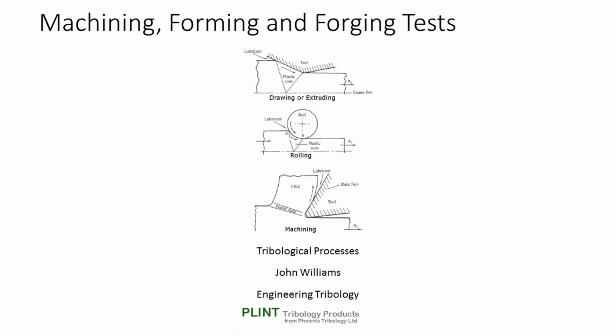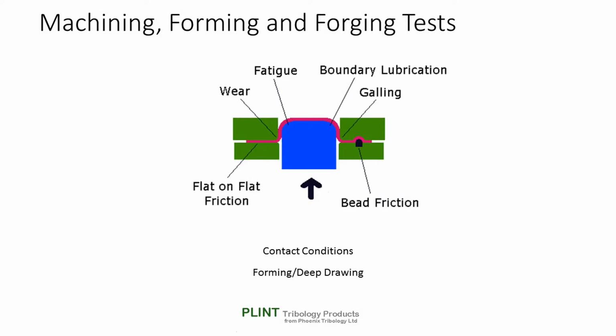It will be apparent from these figures that any experiment that relies on external measurement of force will suffer from an inability to separate deformation or cutting forces from friction forces. Further to this, the majority of such tests will give nothing more than the mean value of the measured force and will fail to identify how the different force components may vary through the contact.